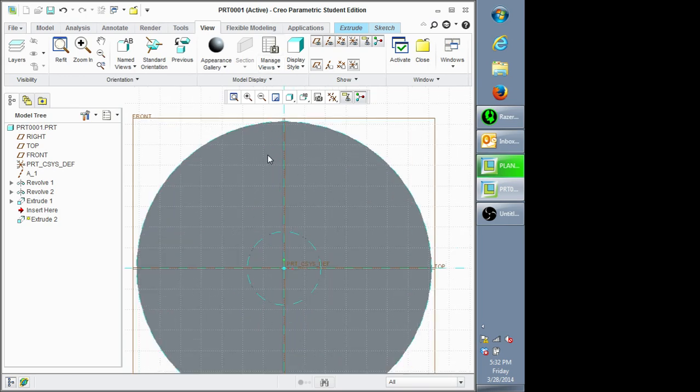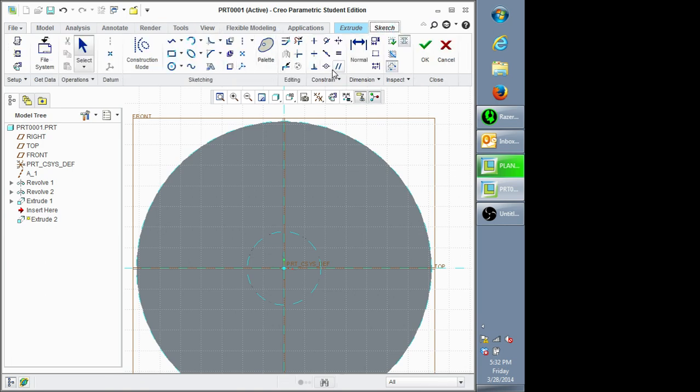So let's set it up. You probably want it to be directly in the middle between these two lines. So let's get the dimension for that between there. So go over here under the dimension in the sketch thing. Use the reference dimension again. Select the inside circle and the outside circle. Go over to the right or the left, doesn't matter. And then middle click. And then the tangent dimension for these two will pop up.